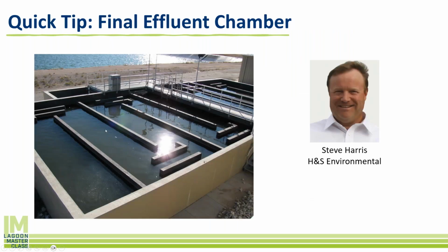A couple of quick tips. This is quick. I'll go through it quick and not tell the story. We have seen in the past erratic high BOD numbers at the end of treatment plants, where you can measure all the way across the continuum. BOD is going down, down, down, down, and the effluent might be 30 milligrams a liter, 30 milligrams a liter, 30 milligrams a liter, and then 200 milligrams a liter, or some high spiky value at unpredictable points.